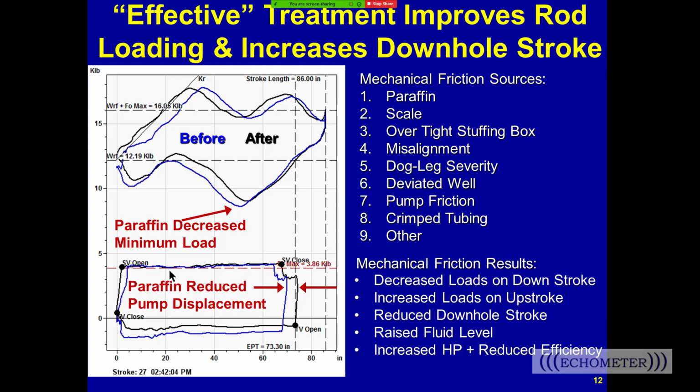So there was a big push to stop using hot oil because you're moving the paraffin problem from well to well, because the problem was in your tank. They started saying to use hot water because there are more molecules of water, and you can get the heat deeper with hot water.